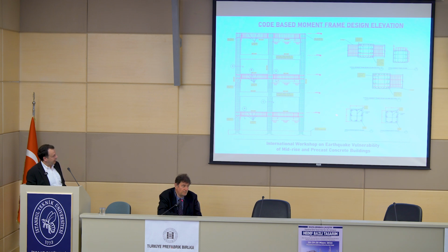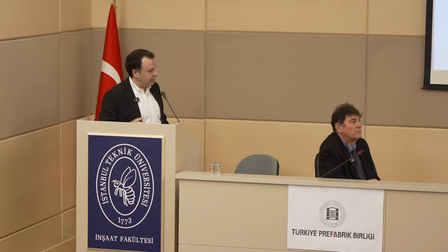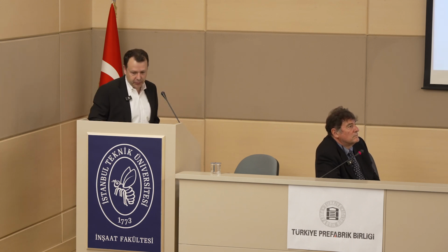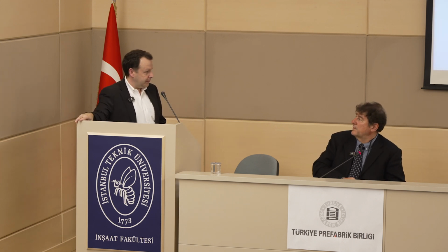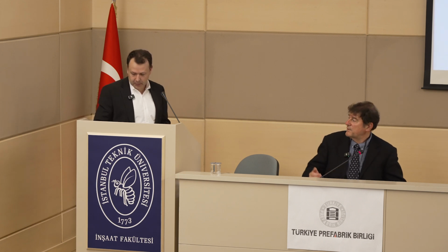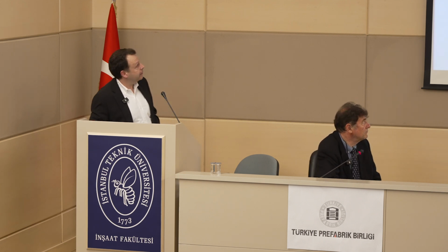Yeah, because we have fewer columns that are moment resisting columns, right? So the sizes, fewer columns that have the larger sizes. And then the other beams are designed for deformation compatibility. I'll explain that as well. But overall, a smaller building in terms of structural elements. Yes. Okay, please go ahead.